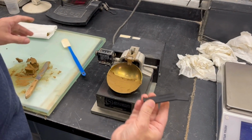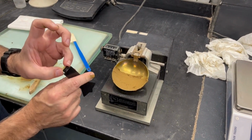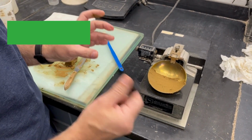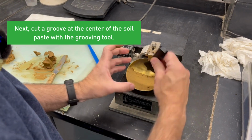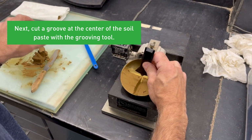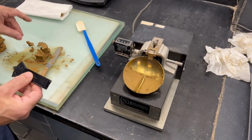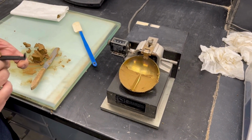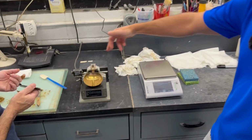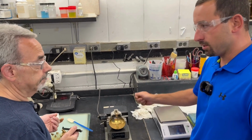Once that gap closes the 1/2 inch, that's where you know you have the right moisture content. It depends on the soil, but sometimes you have to do this in stages rather than taking one quick pass. But the soil's pretty good. So that's the groove right there. We have an automated cup, which is nice. It's going to count for us. There are definitely cups out there that have a little crank, and you just have to count.